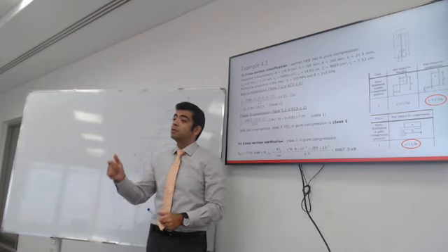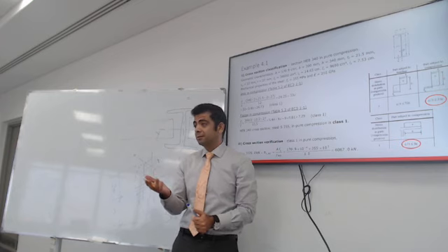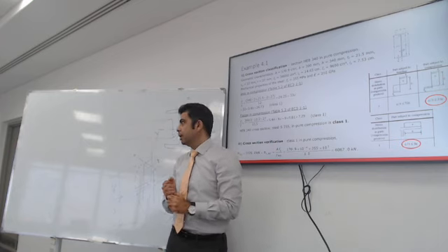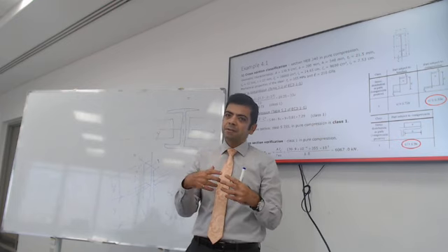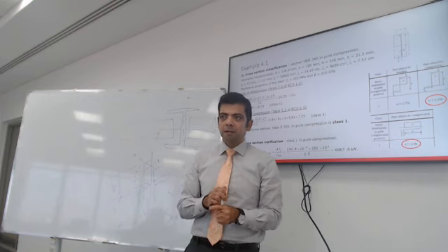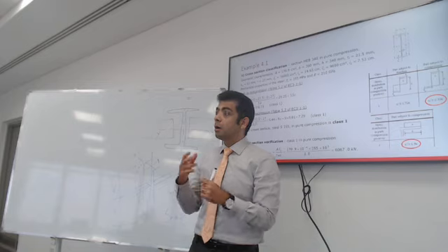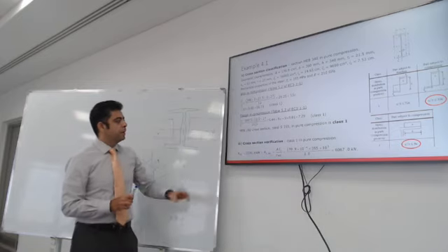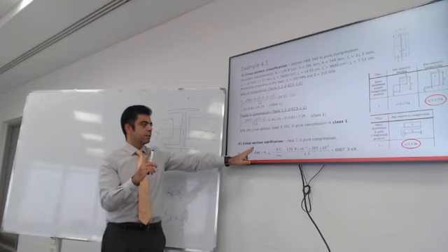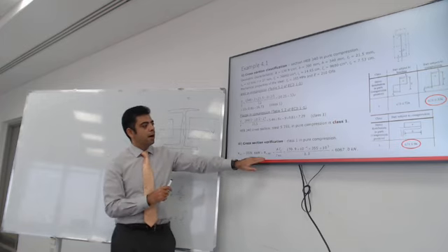We will use the code equations for class 1. If it turned out to be class 3, you use the equations for class 3, which means that it is flimsy and going to be weaker. Section class 1 and class 2 are much stronger and can take much more load. All right, here is the first check, the cross-section verification.